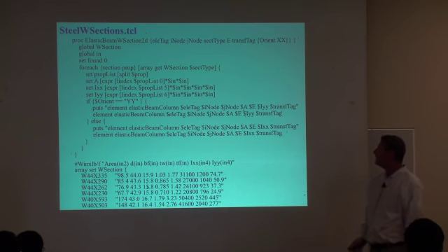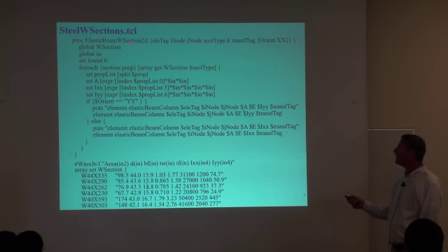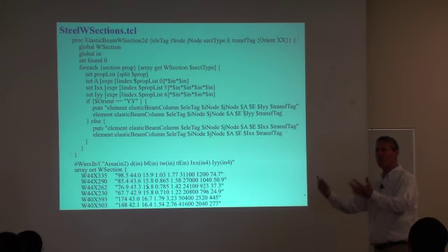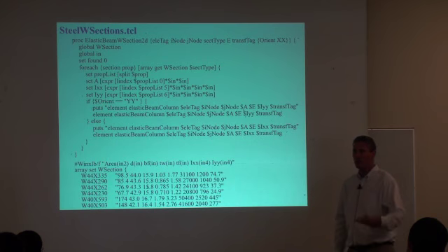So just to show you, this procedure, elastic beam section, is in this file, PLW sections.pickle. All it's doing is going into this large array. Given this is our index, we're looking at this array for these values here. We get the area, I XX from this table, and then we just create our elastic beam column. Here's where we're issuing the fix command. Element elastic beam column. The tag is 2 nodes, A, E, and I, which is just coming straight out of the table. Okay? Again, we've created this procedure to do something we're going to do a lot.